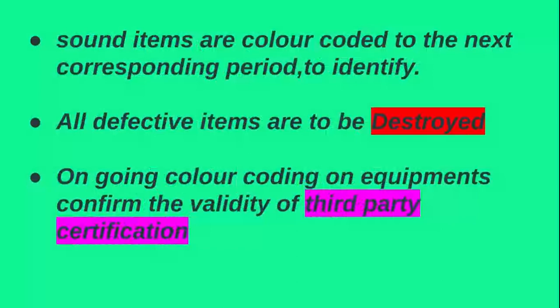All defective items are to be destroyed. If slings, shackles, any lifting gears or any lifting equipment are defective, they are to be destroyed, and inform our supervisors or manager or whoever is responsible for these lifting items.